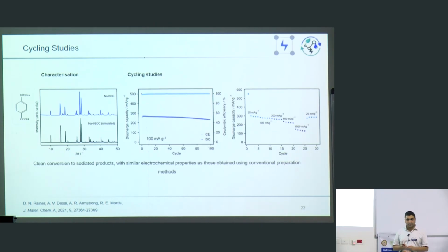Right. Ball milling, is it the friction that actually? It is the friction and the local heating that is caused by the friction. So that's actually a good point, because there is no quantification of the amount of heat that is produced during the synthesis, but there are thermal maps which show that there is some heat that is evolved because of the friction. But that will generate abnormal shape and size of particles. Yes, yes. So that is the thing that you optimize. You have to work around the frequencies of the milling, the sizes of the balls, and of course the particle sizes you start with. So if you know all of that, you can actually work around it, and you can end up getting particles that are very uniform in nature.